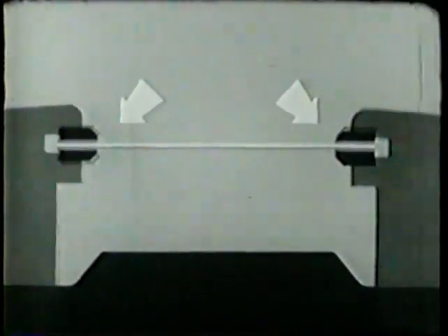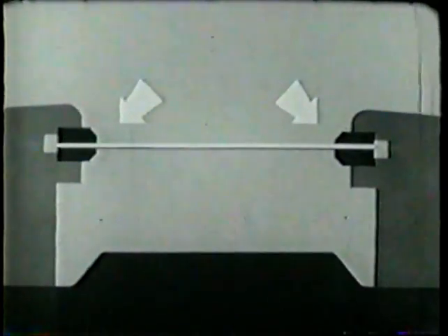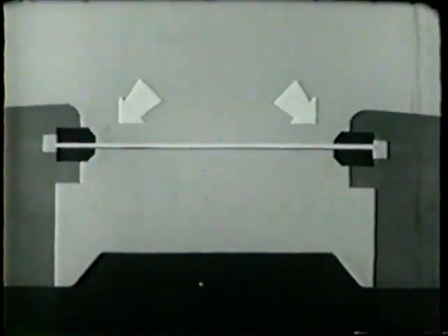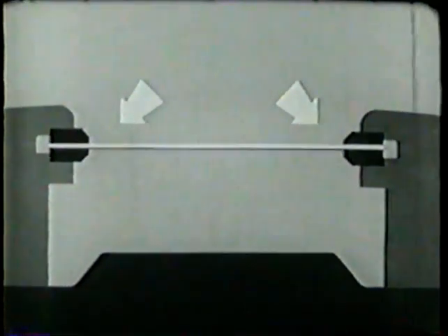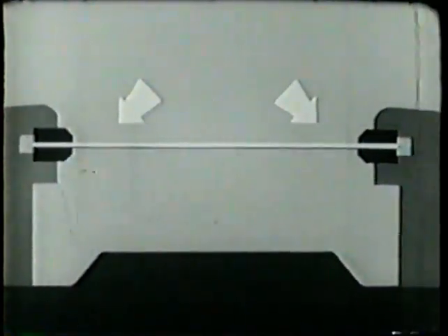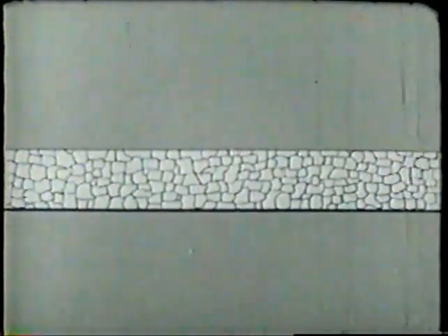The stretching process is based on the action of vise-like grips, in which the edges of the aluminum alloy section are inserted. As the tensile load is applied through the grips, the metal is stretched, the equiax grains becoming elongated and oriented in the direction of the applied load. These grain changes increase the strength and hardness of the metal.